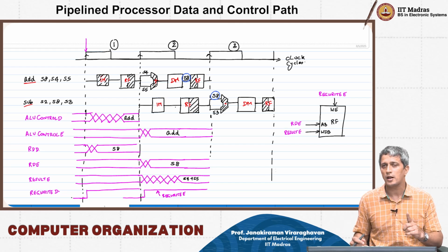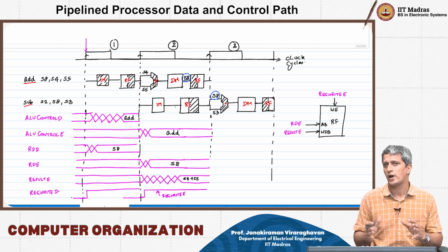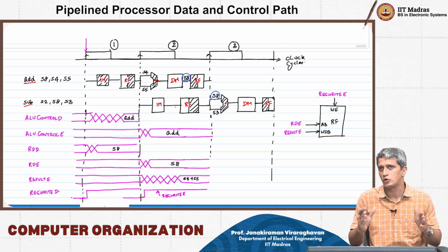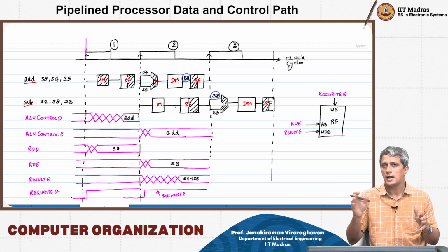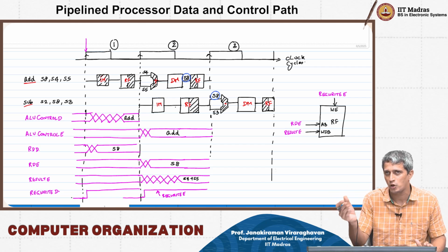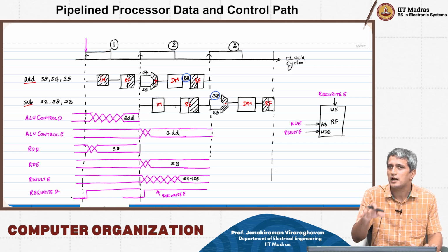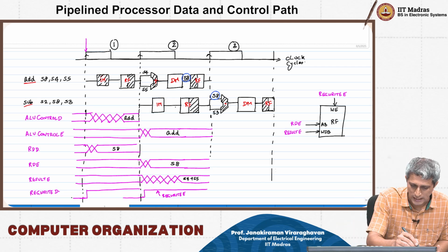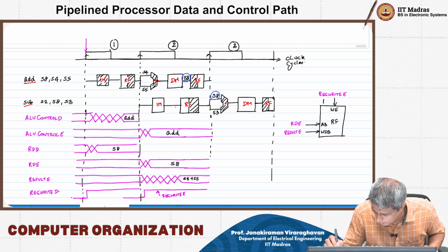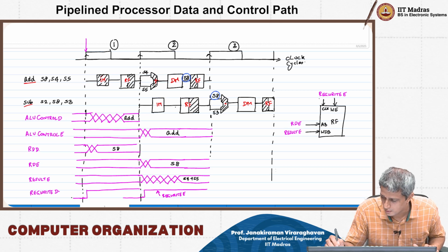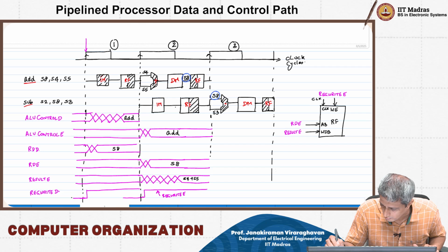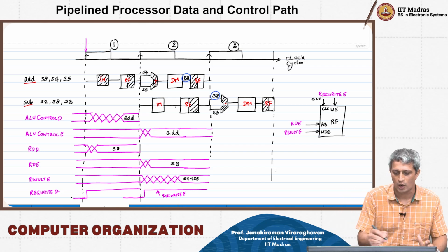However, remember that we are dealing with a sequential write operation. The read in the register file was combinational. Of course, we put a flip-flop after that, and therefore that made it sequential beyond that. However, the register file read is still inherently combinational. So in some sense, there is an important thing here. Let's call this clock, and we give clock here. Remember, this clock is what? This signal.